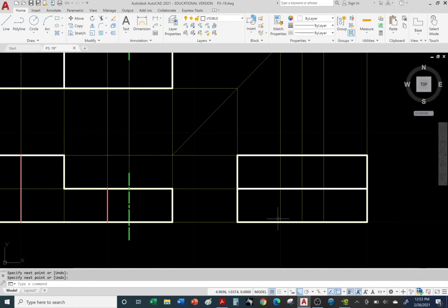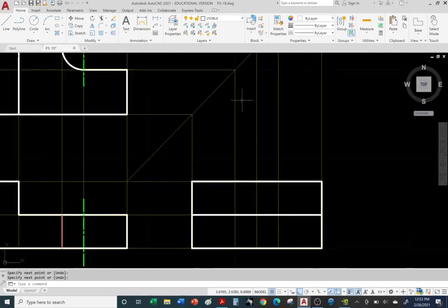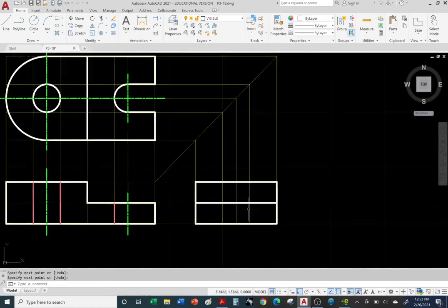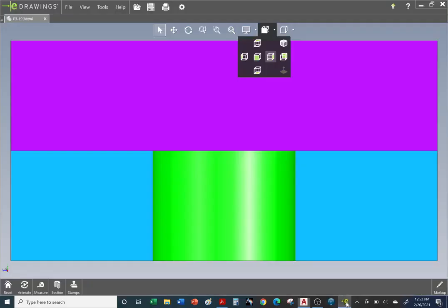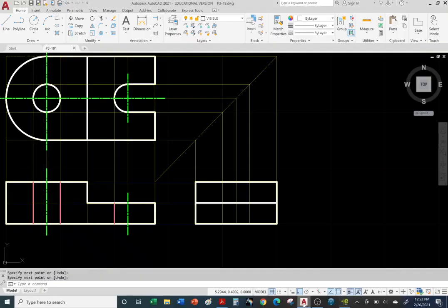Now we need the two small vertical object lines, right? And just to guarantee that it lines up, we can use the top view. You don't have to do this extra geometry, but just to show you how everything lines up.